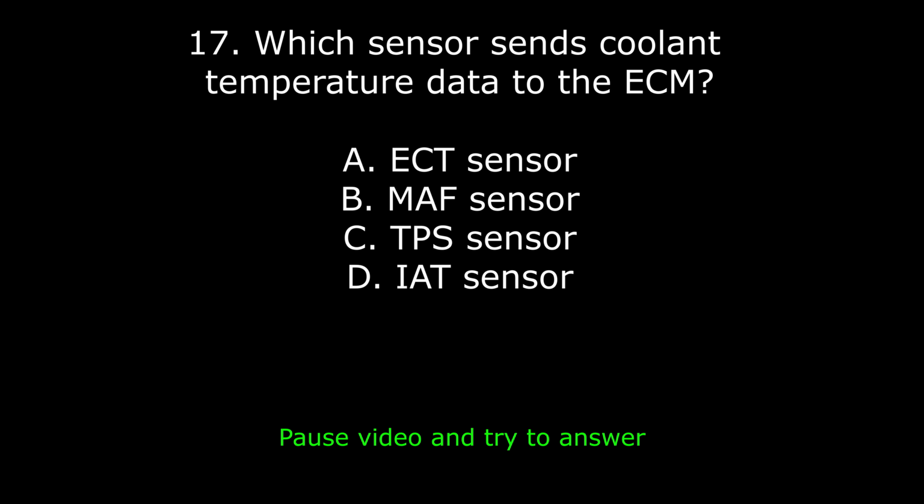40. The cooling fan relay clicks, but fan doesn't run. Cause: A. Bad fan motor. B. Weak battery. C. Faulty PCM. D. Open fuse. Answer: A. Bad fan motor. Relay click means control works. Load side, motor, likely failed.